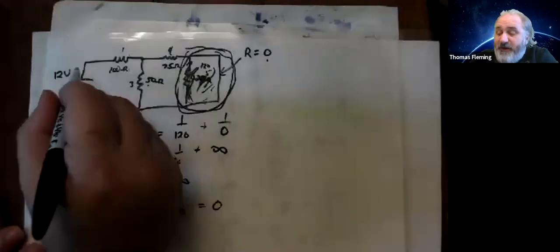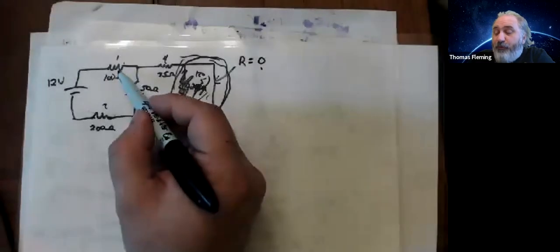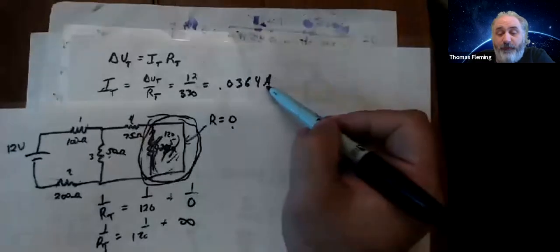Now, it's not the only one. Wait, you said I1 equals I total? Yes, because anything coming out of the battery, that's I total. We know how much comes out of the battery is this much, right? If it comes out of the battery, it's got to go through resistor 1. So that means resistor 1 has to have that much current. Is that the only one?